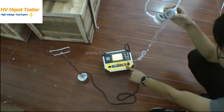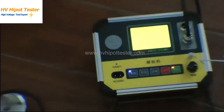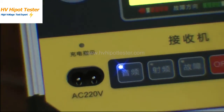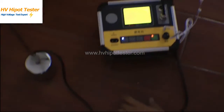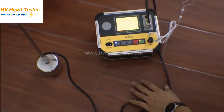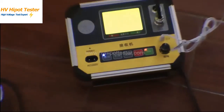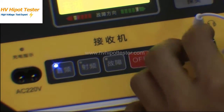Turn on the machine and press the VF key. From the earphone, we can hear the discharge from the underground. The gain button can adjust the size of the sound. Above shows how to use the shock sensor.